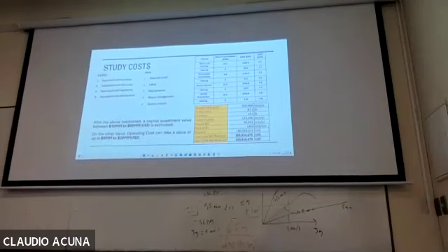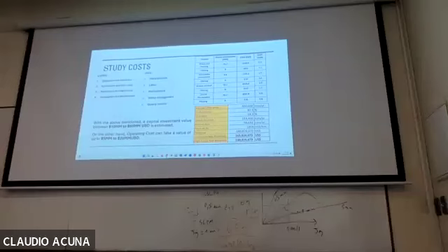You can divide that into three or four rows. You will end up with 20 or 40 cubic meter reactors, in order to make a rough estimate of the cost. So always come to a rational number, come to liters per minute. You have 30 liters per minute, something like that. 1,000 liters per minute is big. You have to have a feeling for how big the equipment is. You don't need to show that, is my advice, in order to check your numbers.